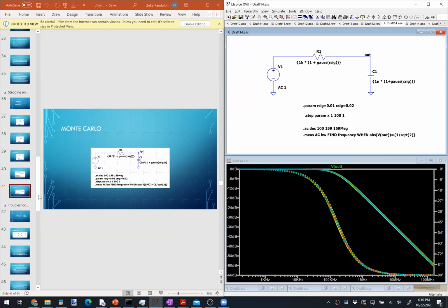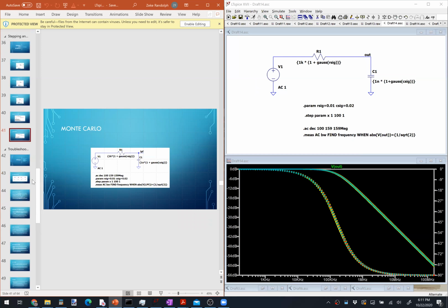Any questions there? That's showing how you can verify that a circuit should function in the face of parameter variations with manufacturing or the life of the circuit or what have you. And that's another thing that simulation is really handy for, because instead of having to build, say, 100,000 circuits before you find that some of them fail your specifications, if you can simulate your circuit across process corners or statistical variation, then you can at the very least get a good sense of what the statistical distribution of your circuit will be in manufacturing. Before you actually build 100,000 of them, you can just simulate 100,000 of them and verify, to a reasonable degree of confidence, that the circuit should work under those circumstances as well. It's just a rehashing of the old theme that simulation is cheaper and easier than actually building the circuit.